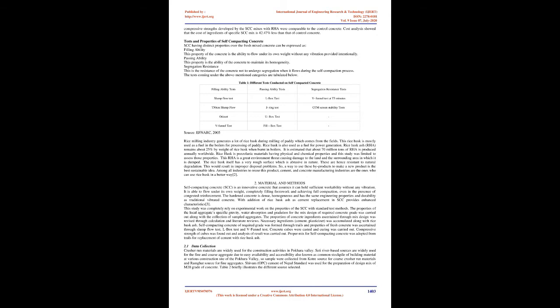Segregation resistance. This is the resistance of the concrete not to undergo segregation when it flows during the self-compaction process. The tests coming under the above-mentioned categories are tabulated below.